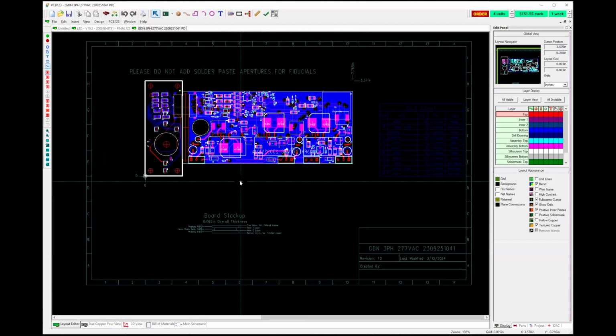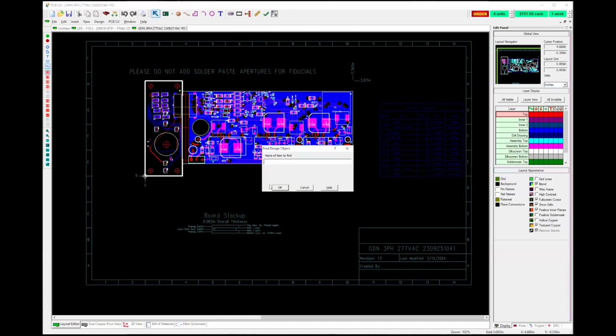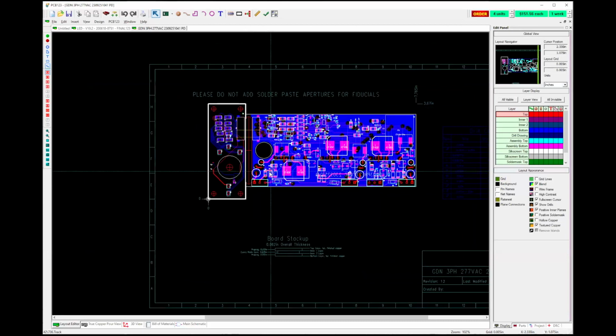And then I'll take a paper copy of the schematic. I'll just print it out to whatever size I can see the reference designators, and I'll select the parts by reference designator and move them to where I think they should go. So to select a part, you just type an F to find, and then you enter the part name. Let's go with something easy. R10. That puts your cursor right on the R10.